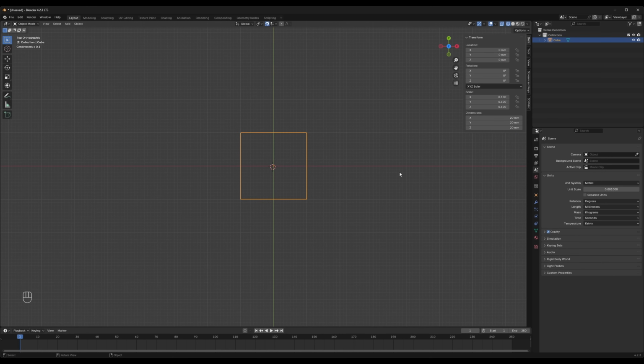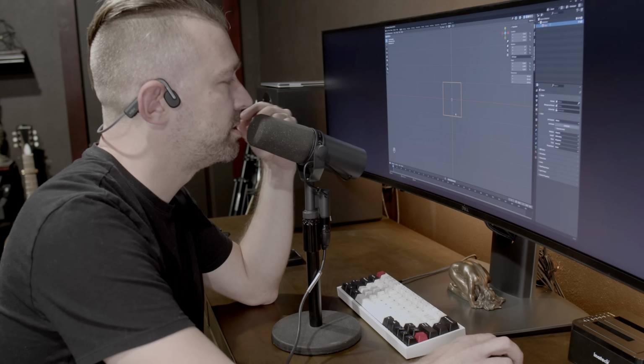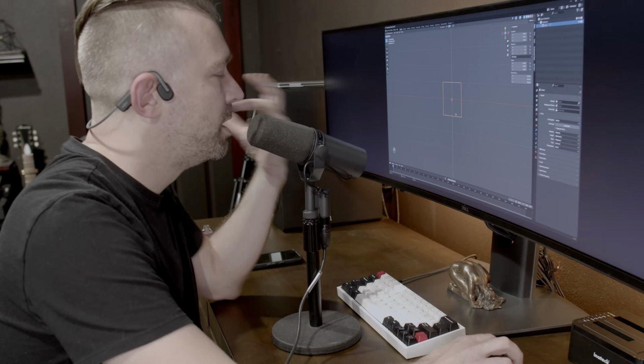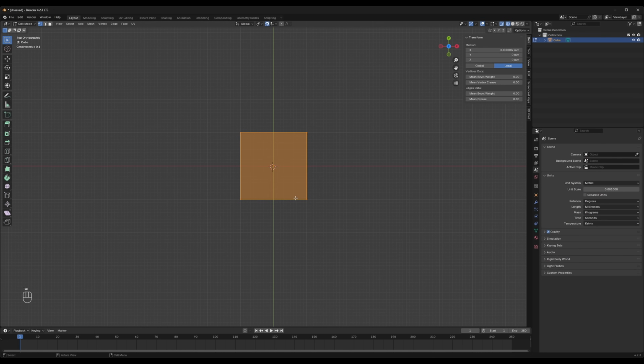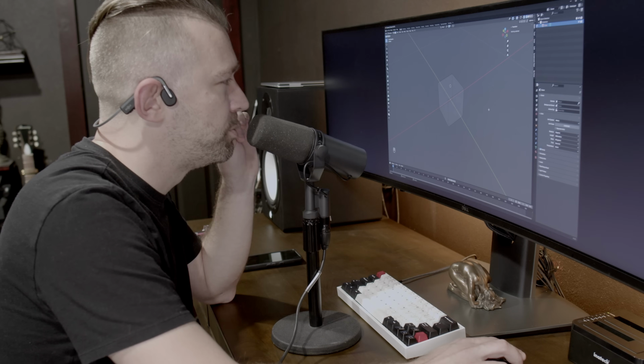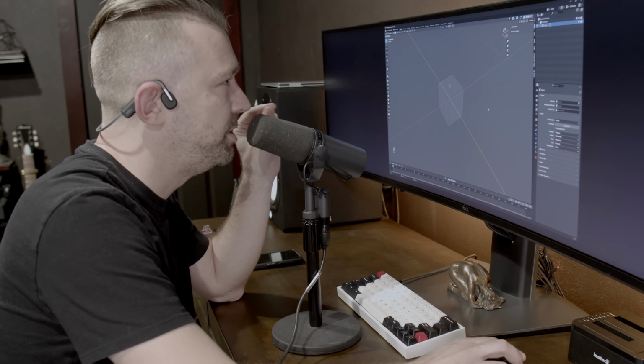So from the top of our grid at the Z-axis, we still have our cube here, our 20 by 20 millimeter. Now remember, the bottom of the desk is 40 millimeters offset to the front from the frame. So we need to adjust this cube. And we're going to do this by clicking the object and then hitting Tab to go into edit mode. Once we're in edit mode, we have 3 options up here. We have options for the vertices, the edges, and the faces. Depending on what you're editing, you can select 1 for vertices, 2 for edges, and 3 for faces. And this really is dependent on what you're editing and what you need to do.